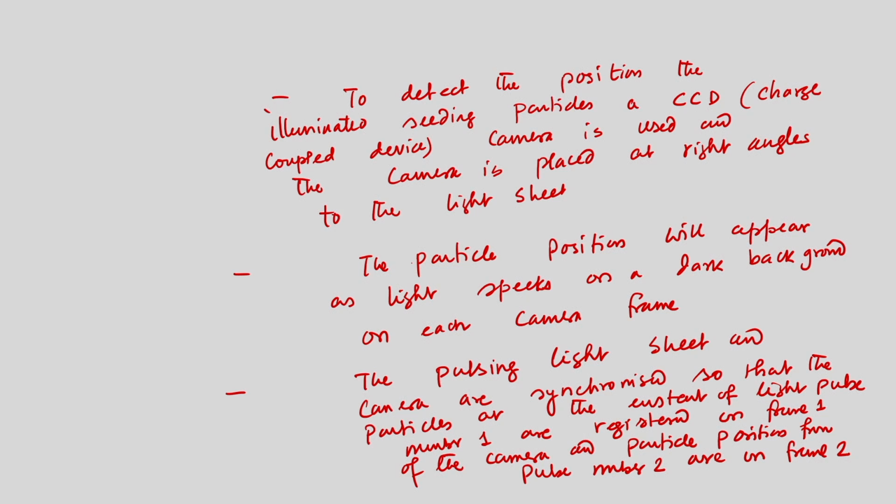This was not possible in older generation CCD, where we had to capture all the positions on the same frame, but this is not the case with present-day CCD cameras. Since the particle positions are captured with a pulse, that is called the stroboscopic effect, that is what we have discussed. So, we will have a continuous movement with a short number of instantaneous movements.